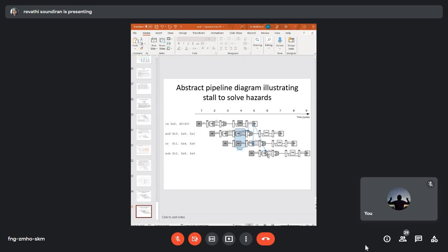This unused stage that is propagated through the pipeline is called a bubble. It is very similar to the no operation, NOP, that you write in your software programs. So that is how you resolve the data dependency problem, or data hazard, in your pipelining architecture.